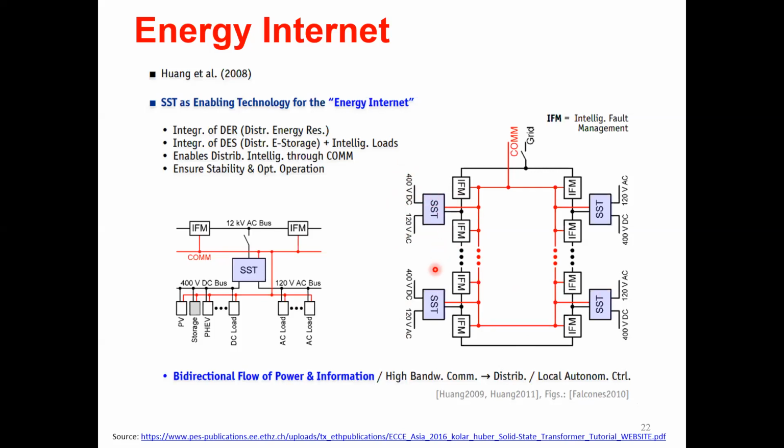This is a concept that has been floated for a long time now. You can see this is 2008, and some places like the naval ships in the US are trying to adopt something like this for improved resiliency and safety of their ships. So it is getting to be more realistic, but there's still a long way to go. Again, because of the reliability of the solid state transformer itself and the losses in the system, who will pay for it, right? Ultimately everything comes down to the cost. If the solid state transformer is only 97% efficient, whereas a simple line or an inverter would have been 98 or 99% efficient, you have to think about all those in perspective.